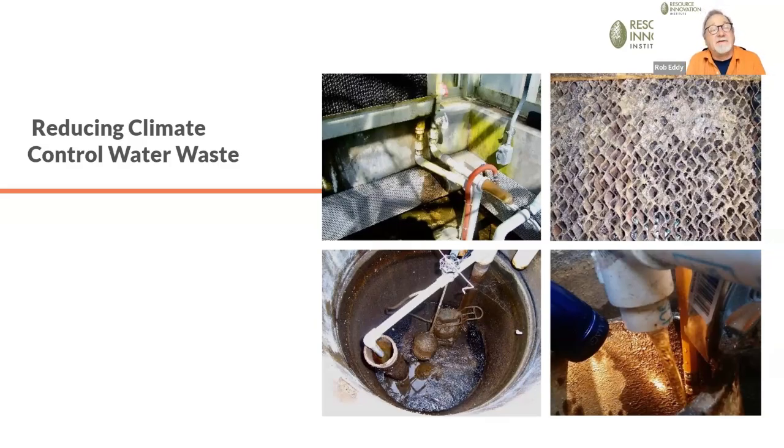But because of that, if you don't adjust these pads for their flow rate and then the bleed off rate, which you're trying to bleed a little bit of that water off all the time, otherwise it concentrates with minerals due to the evaporation. If you don't adjust those well and do that unglamorous work, you could be wasting, for an acre greenhouse, millions of gallons of water a summer, a cooling season. I know. Okay. Next slide, please.